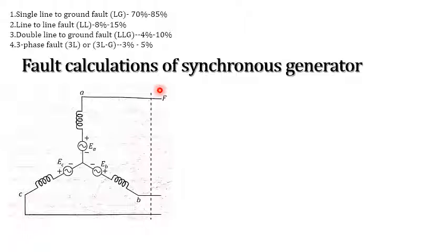The fault may be unsymmetrical, but to the left of point F the system is completely symmetrical. Hence the current of a given sequence produces a voltage drop of the same sequence only, meaning the sequence impedances are uncoupled, since the alternator generates balanced voltage only.